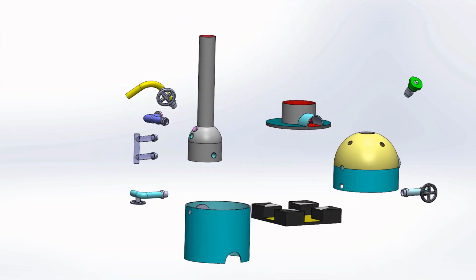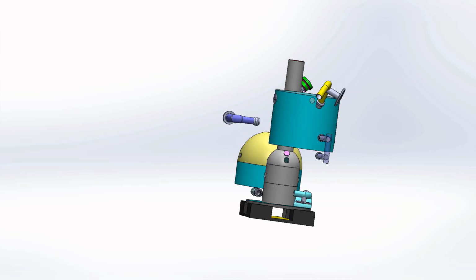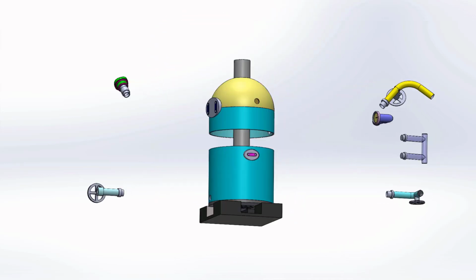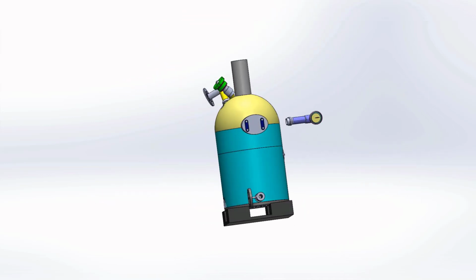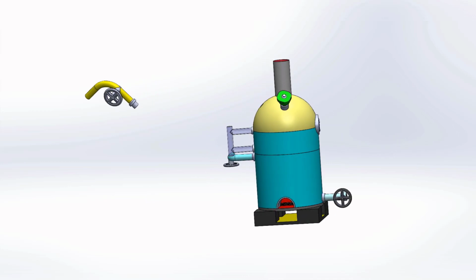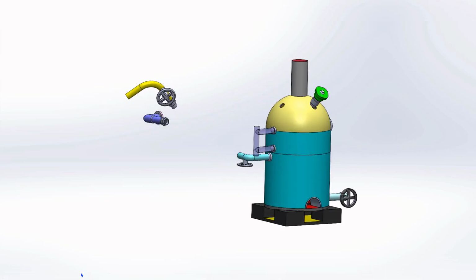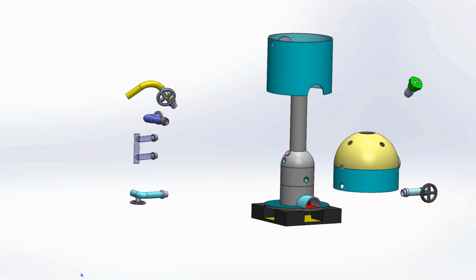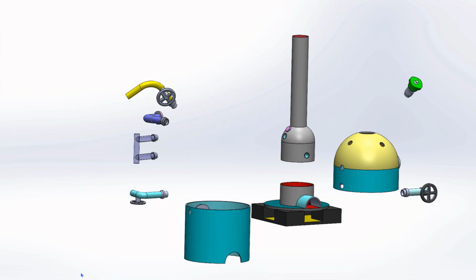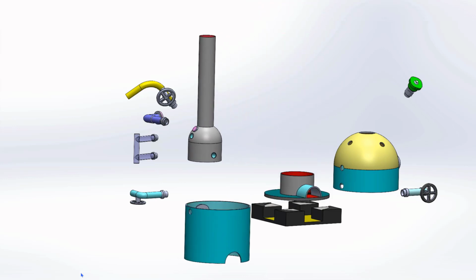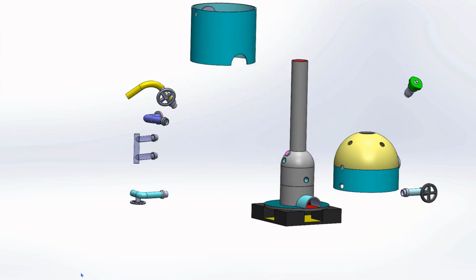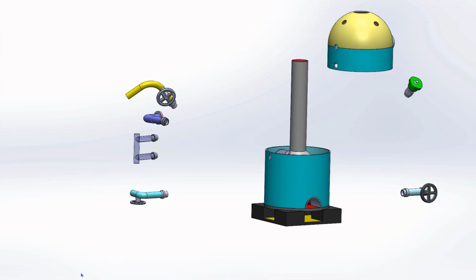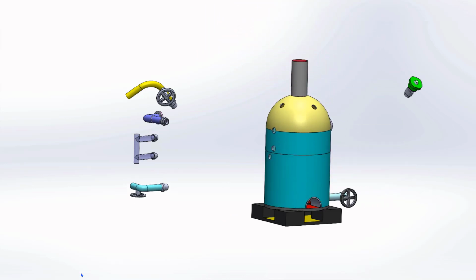And one of the important boiler mountings is the fusible plug. A fusible plug is a plug made of low melting point alloy. It is placed above the furnace. If the water level goes down, the fusible plug is melted much before the boiler material due to overheating. The water enters the furnace under pressure and the fire is extinguished, and it avoids the explosion of the boiler.